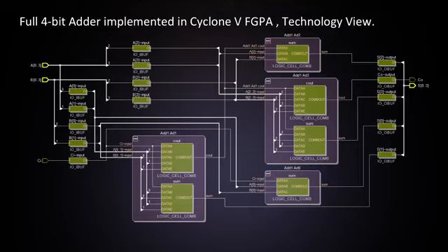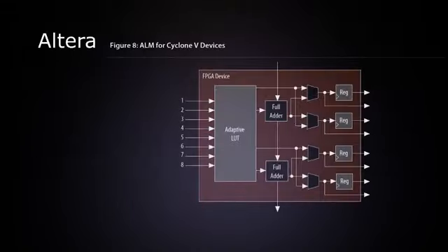Although the use of the carry look-ahead or other more sophisticated adder circuits may be beneficial in some applications, the presence of coarser-grained FPGA architectures may make this unnecessary in many cases. The implementation you choose needs to be determined on a case-by-case basis, as there are many trade-offs that may not be obvious at first. This is not unusual in FPGA design. This is part of what makes it so interesting. Furthermore, the Cyclone 5 logic cell, called the Adaptive Logic Module, or ALM, includes fast carry chains and full adder implementations as part of the logic cell, which makes implementation of adders particularly fast and efficient.